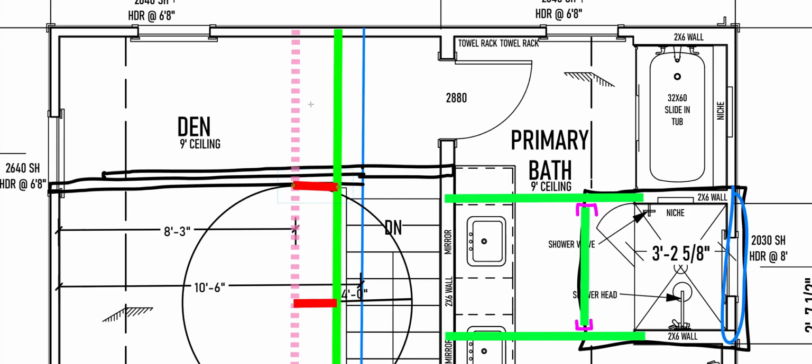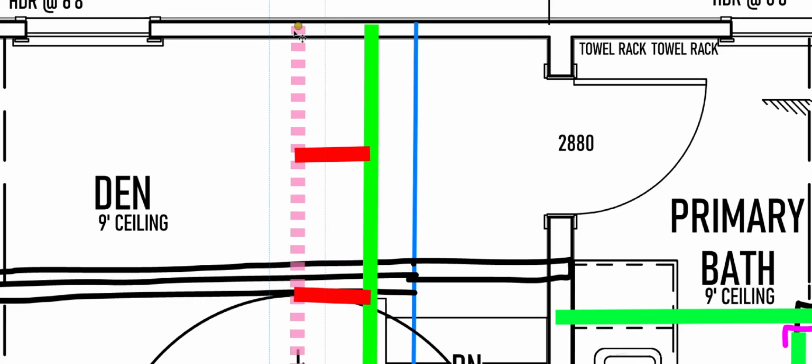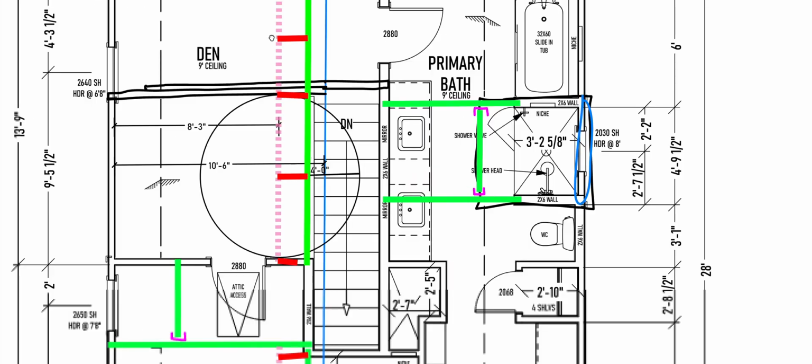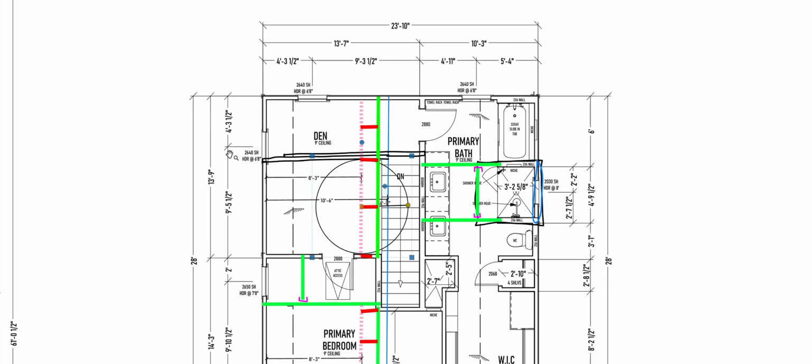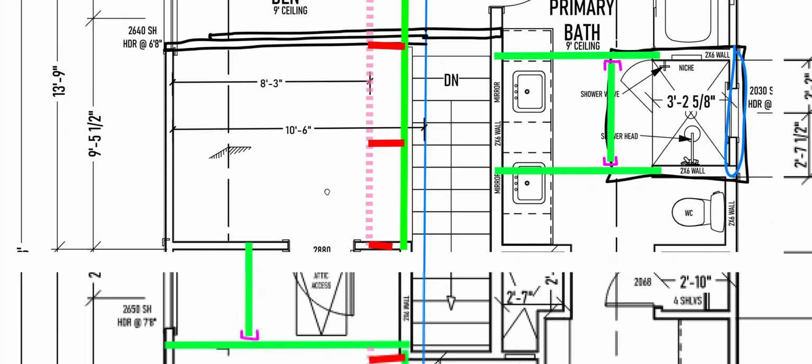And that's less than 4 feet. So let's just put one in the middle of that span. Now, realistically, the purlin's not going to stop in the wall. It's going to stop somewhere over here maybe, or it'll stop on the last rafter, whatever, but you get the idea. Okay, so that takes care of these rafters.